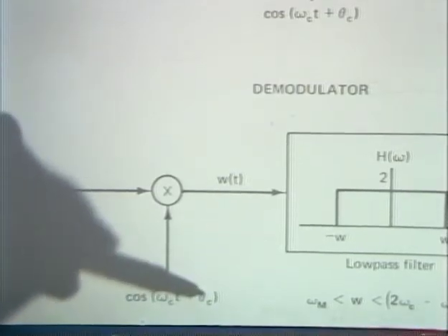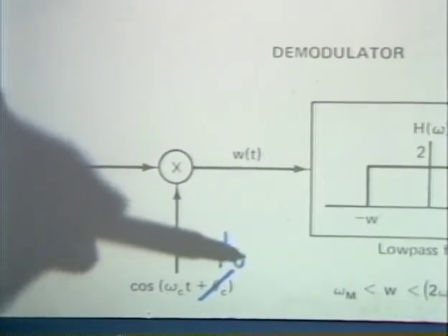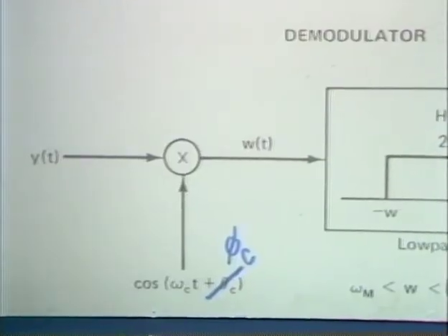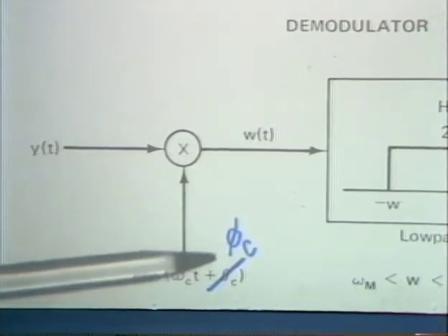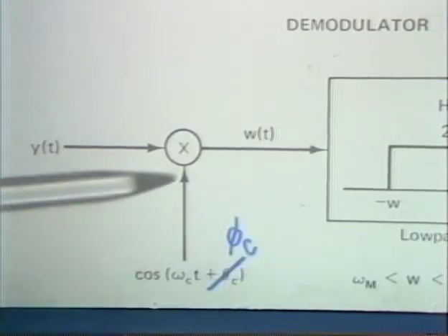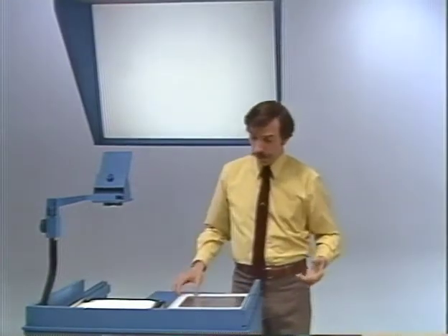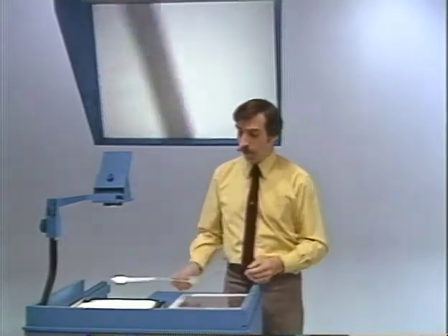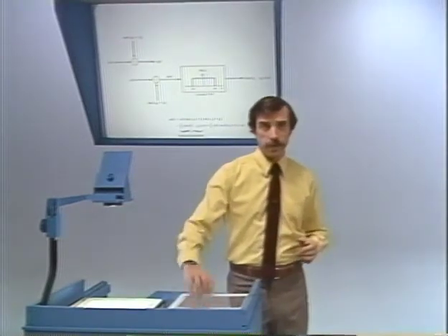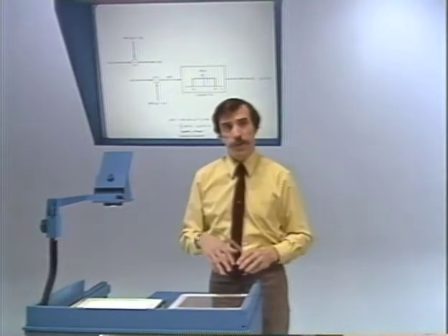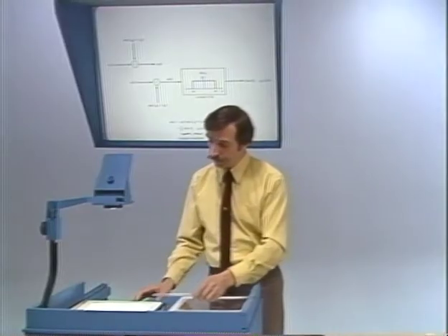And so what we want to examine now, more generally, is what the consequence might be and the solution to the resulting problems if we don't have synchronization between the modulator and demodulator, synchronization in terms of phase. And there also, by the way, is another problem, which is the issue of synchronization in frequency. That's examined more in the text, and what I'll focus on here is just the issue of synchronization in phase to give you some sense of what the issue is.